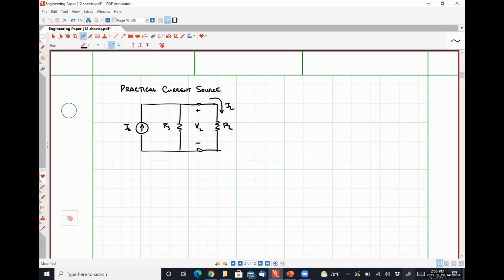In truth, current sources are just transistor circuits where there is a relationship between the input voltage that you apply and the amount of current that you get out. So anything approaching a true ideal independent current source really doesn't actually practically exist. But we can still logically work our way around to this problem, right? And so we are going to get a pretty similar graph.